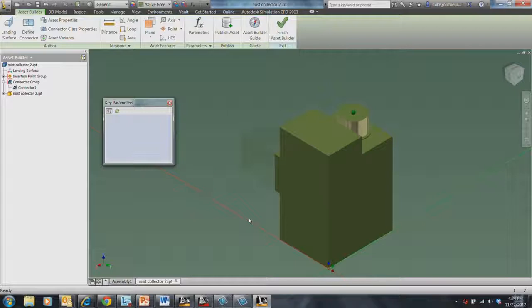AutoCAD 2013, that's a good question. The question is, basically, will Inventor read in the parameters that you did in a 2D parametric sketch? Could you have extruded inside AutoCAD? Absolutely, but the only problem is you wouldn't have parametric control of it. It'd just be a solid. Not to a base solid, no. Absolutely. I can change the diameter of the stack if I want to. I can do whatever I want. You can in 2D.